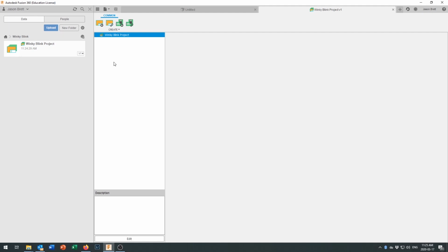Then we're going to use that schematic, once we know we've got a good schematic, to create a printed circuit board or PCB file. And that one is going to be really concerned about all the component sizes and the traces and all the details of actually physically manufacturing a board that accomplishes the ideas that you lay out in the schematic.